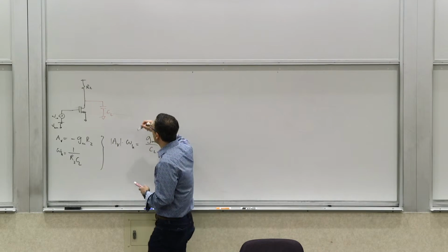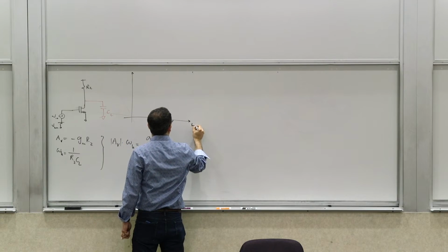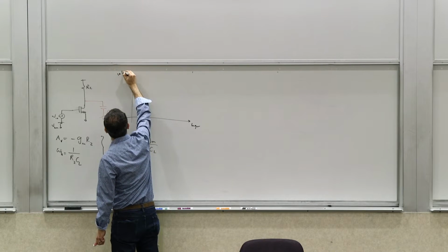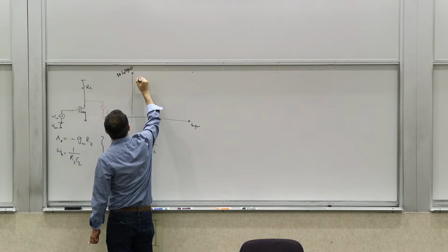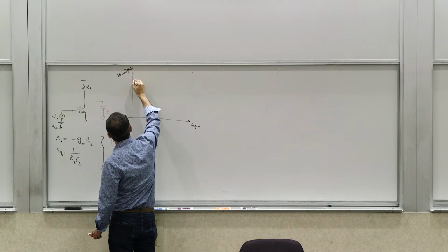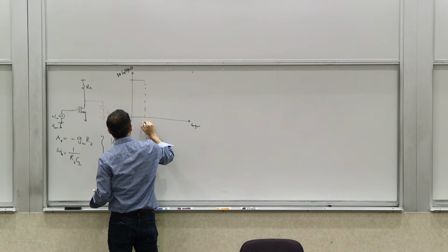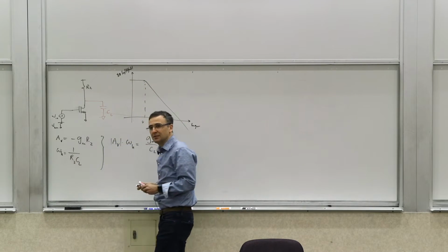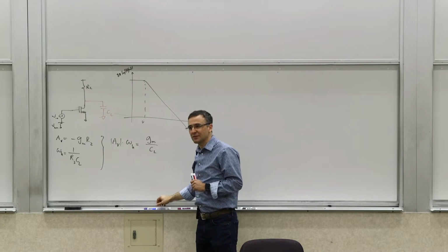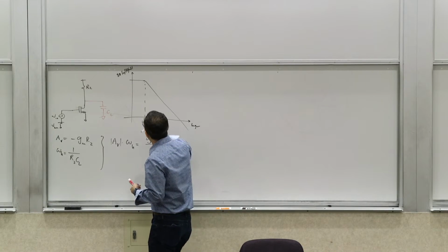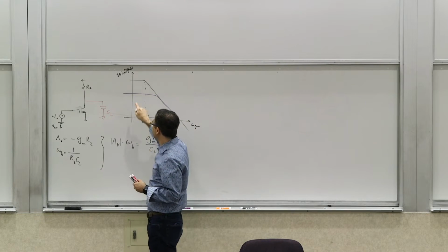So what this means is that if I pick a large resistor, try to get a lot of gain, right? So this is log of omega, and then this is 10 log of the magnitude of H of j omega. Or 20 log of H of j omega. Then what you see is that if I pick a large R, I will get a large value here, but my omega H is going to be small. So I'm going to drop earlier, not faster, drop earlier. Now, if I reduce my resistor, my omega H will go up, but my gain is lower.